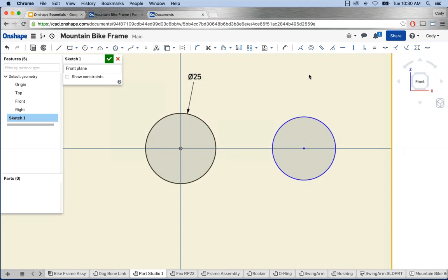So let's move forward. Again, dimension. I'll dimension the second circle. This time, diameter of 20. Again, still not fully defined, but closer. Right? So the circle diameter cannot be changed, but the distance is not defined. And one of the best ways to understand why it's underdefined is just to left click and drag it and see where it moves. Remember that you can always undo. And that's one important thing I haven't pointed out yet. You do have an undo here in the top left, which allows you to go back one step.